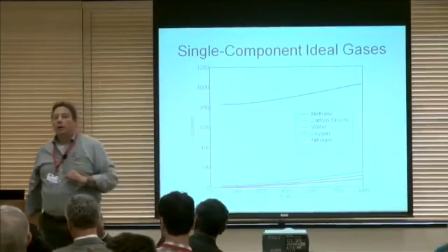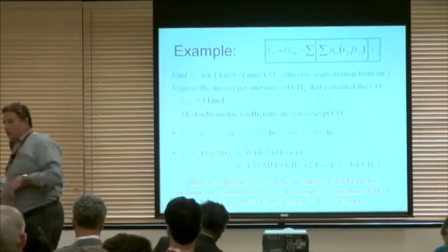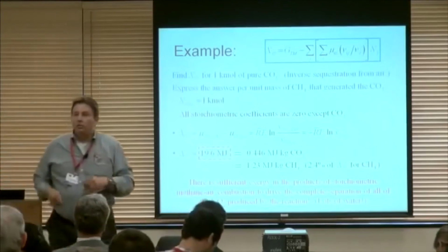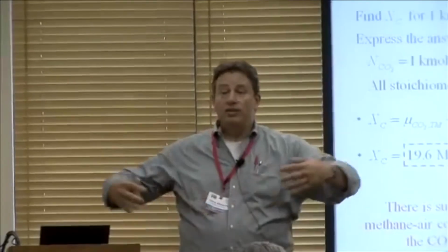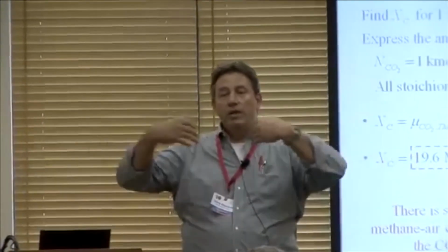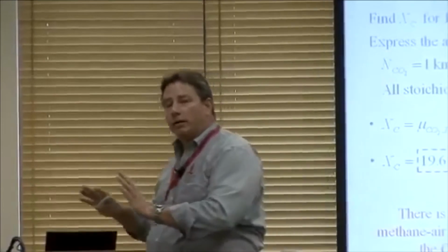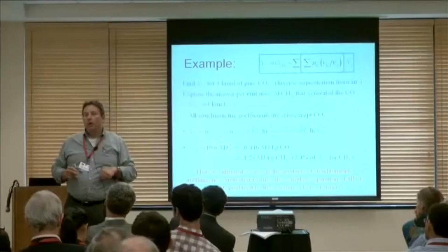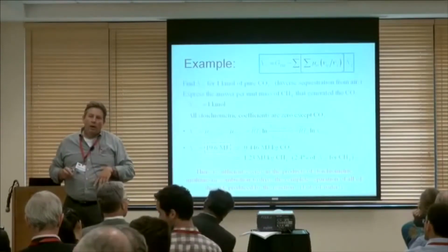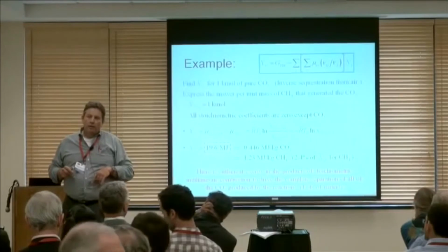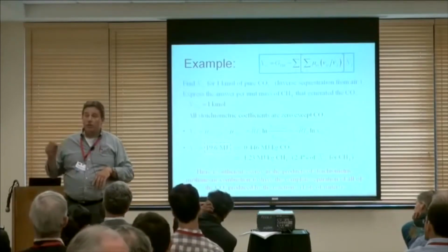On that previous slide, what's the nature of the diffusive energy? Diffusion. Just molecular diffusion. So in all of these cases, you have something that wants to generate entropy. Energy wants to disperse. That's the essence of the second law. When you go to take work, the idea is you go along for the ride, right? And what you do is you restrain it in the process of going along for the ride, and that restraint absolutely requires work. That's the essence of the Gouy-Stodola theorem. The abundance of species in the exhaust, that change in distribution, has enough exergy to power the separation of its own CO2.